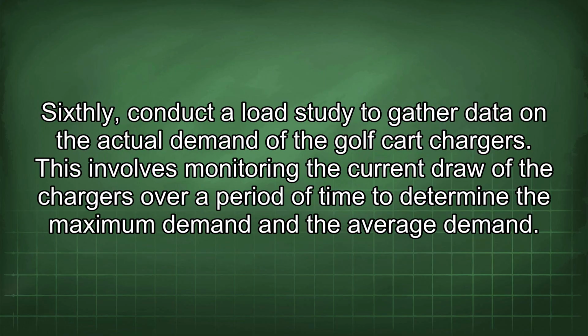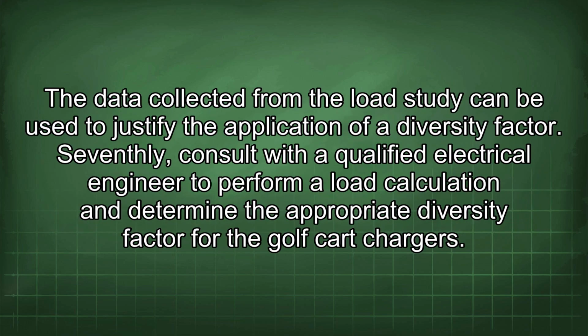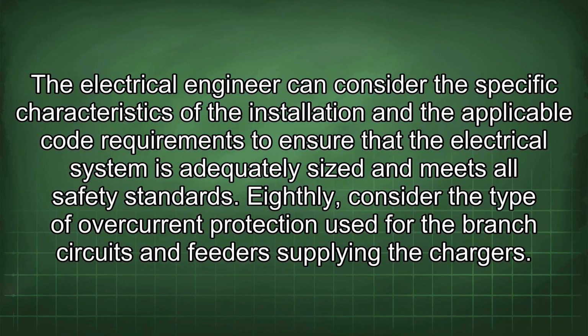Sixthly, conduct a load study to gather data on the actual demand of the golf cart chargers. This involves monitoring the current draw of the chargers over a period of time to determine the maximum demand and the average demand. The data collected from the load study can be used to justify the application of a diversity factor. Seventhly, consult with a qualified electrical engineer to perform a load calculation and determine the appropriate diversity factor for the golf cart chargers. The electrical engineer can consider the specific characteristics of the installation and the applicable code requirements to ensure that the electrical system is adequately sized and meets all safety standards.